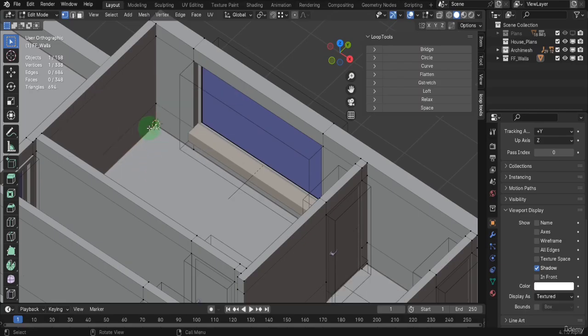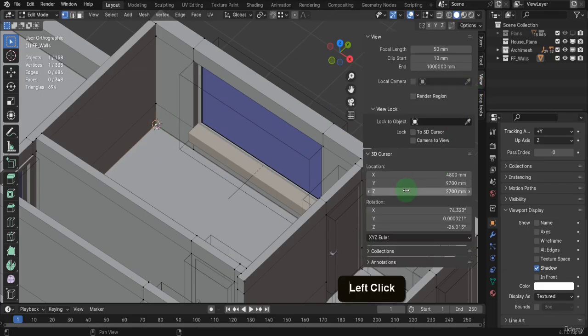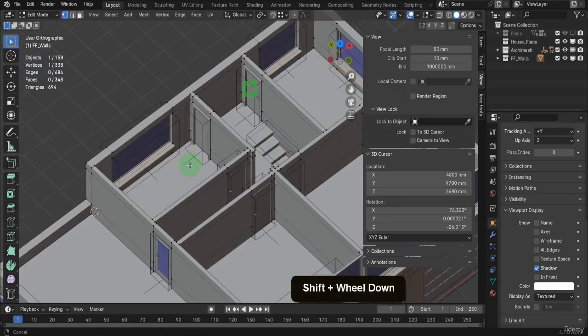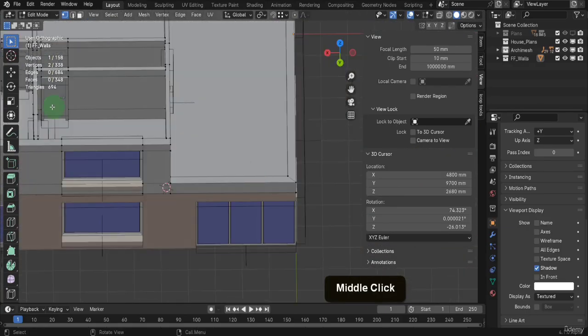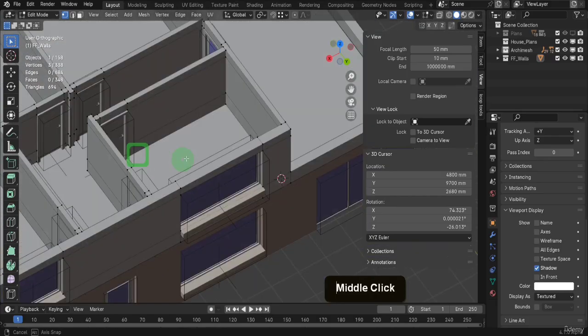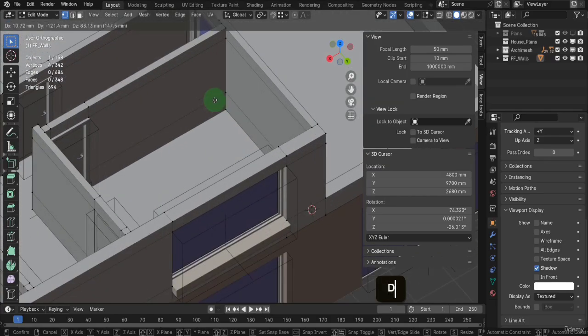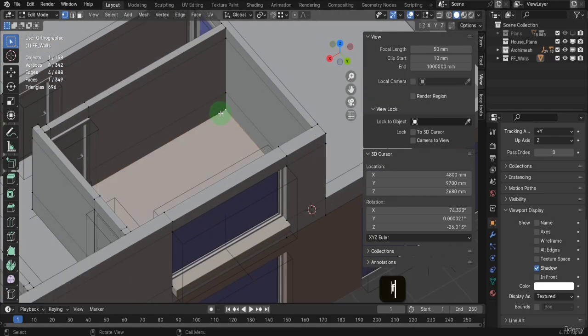This will then need to be lowered 20 mm, so open the View tab. In the Z field, we can click and remove the mm. Then add in a -20 at the back of this value and subtract that distance. Back in the room, we can shift select the 4 corner vertices. Press Shift+D and right click. Press F and create a face. Press P and we can separate selection.